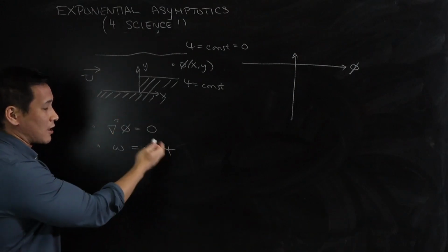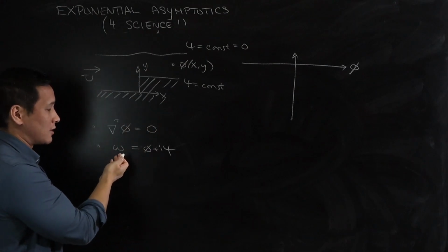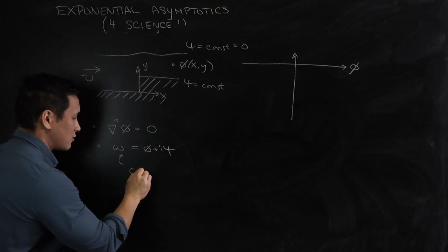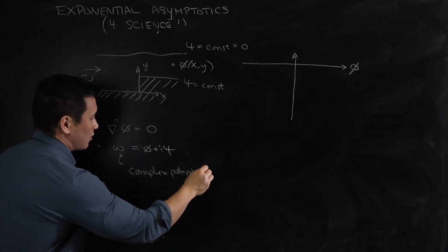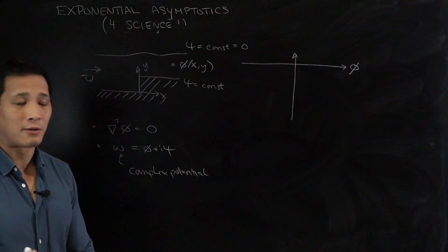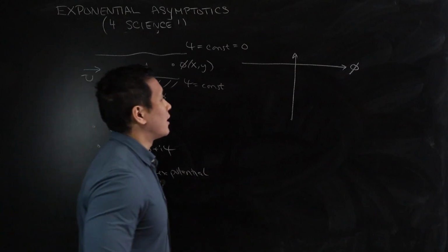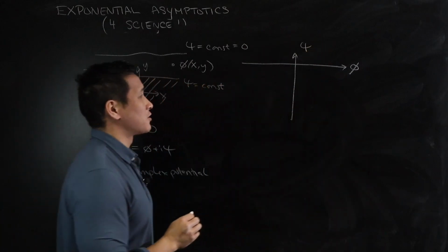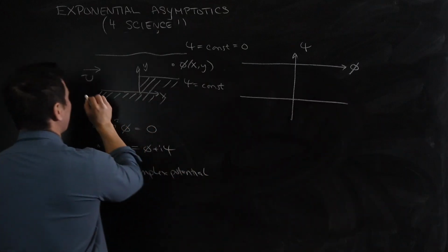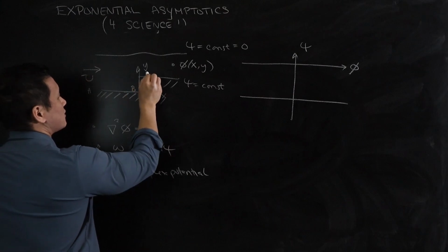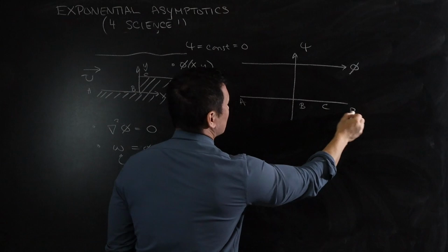Okay, so this is the complex variable nicety that you have, that if you're trying to solve a Laplace equation, you can introduce what's called this complex potential. And then there are two unknowns in this problem. There's a phi and a psi, your potential and your stream function. And so you can plot the domain as a function of phi and psi, and it basically lies within a strip. So if I call this A, B, C, D, this is now A, B, C, D.